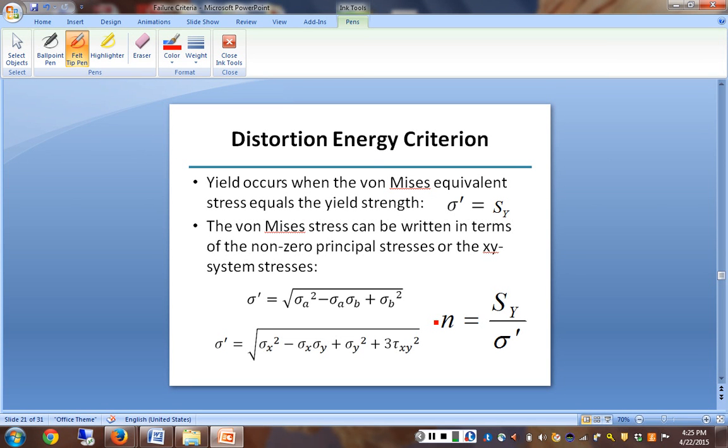So that's why it's report. And if you pull in SolidWorks, you can look at the X direction, or I think SolidWorks might call it IJK, but you can look at it in any of the 3 component directions, or you can look at the von Mises equivalent. You can do that either of these ways, and to get the factor of safety, you just take the tensile yield and put it on the denominator, and that's your criteria.